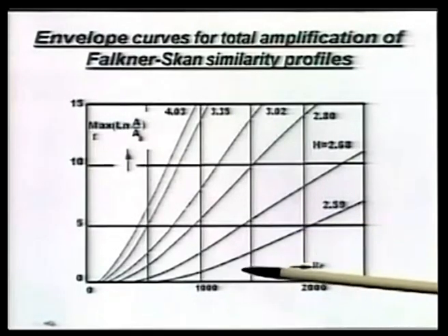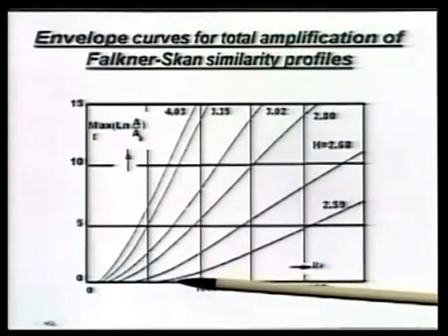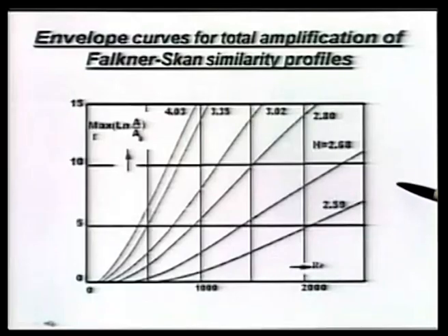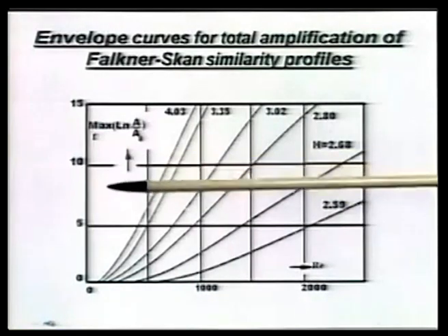So, you can see that for a Blasius profile to go unstable, and if I say e to the power 9, it would have to traverse a much longer distance. But if you look at 2.68, it would indicate that by this time that value N equal to 9 has reached here, right.